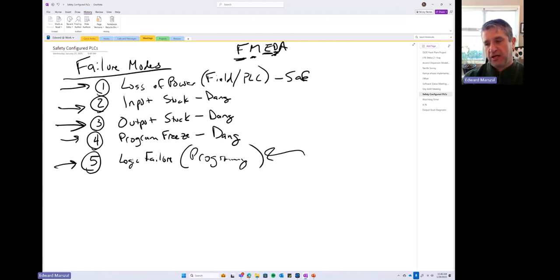What you need to ask yourself is, do I want to do all this engineering myself, or do I just want to let the equipment vendor take care of it for me? And if you buy a SIL 3 certified safety PLC, I can pretty much guarantee you that the equipment vendor did all the thinking, all the engineering, and all the programming for you, and all these requirements are going to be met out of the box. If you buy your commercial off-the-shelf PLC, none of this stuff has been done, and you're going to be responsible for doing 100% of it by yourself.